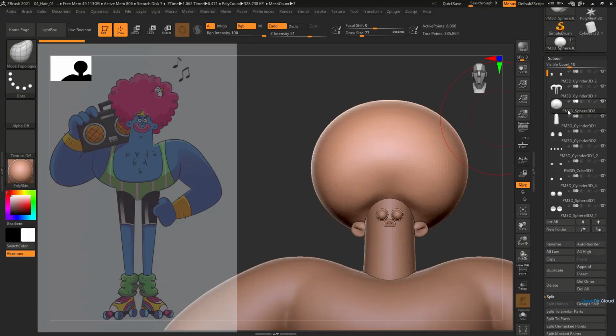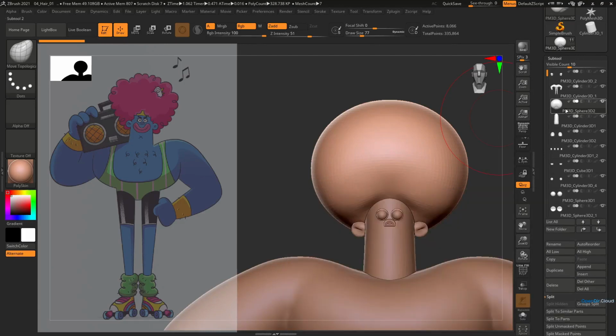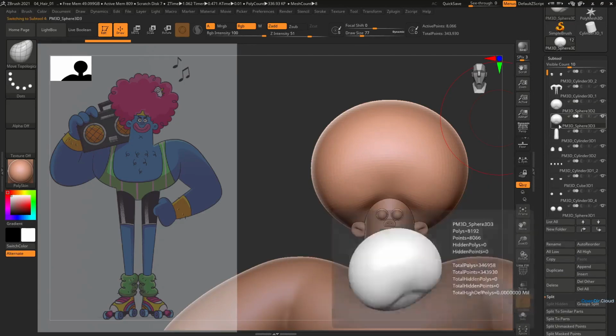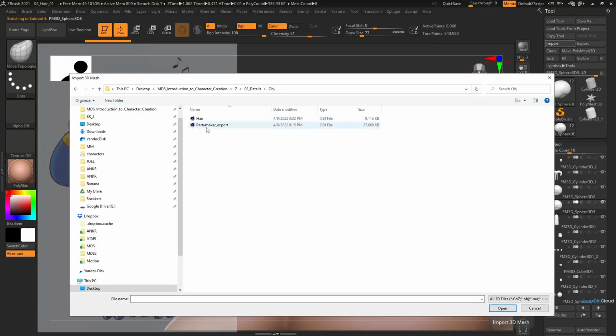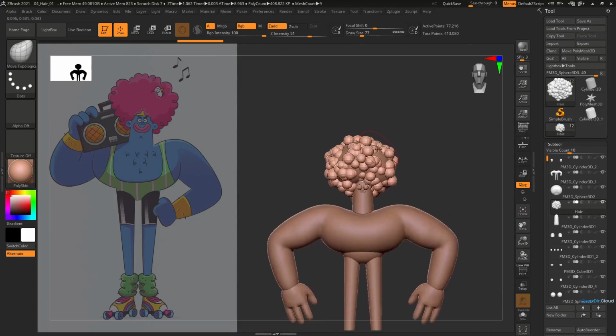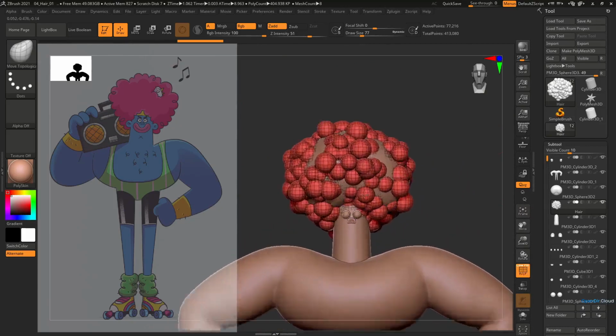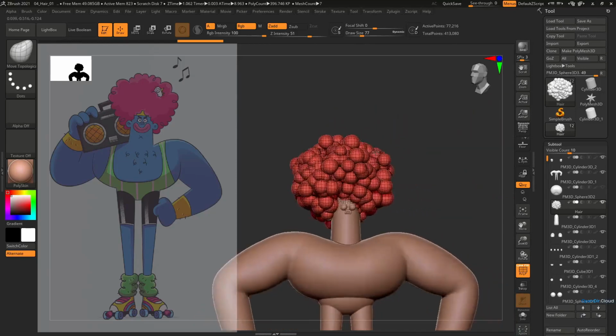Let's go back to ZBrush, and before importing, it's really important to either create a new subtool or copy an existing one. I'll just copy the head of hair. Now when we click Import and select our hair file, it will completely substitute the selected subtool. So when you import, you should remember to select the unnecessary subtool to ensure that you don't delete anything important. I want to slightly adjust the head of hair. I'll hide the old blank.